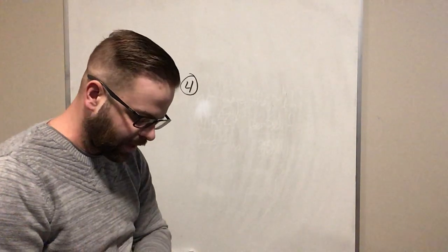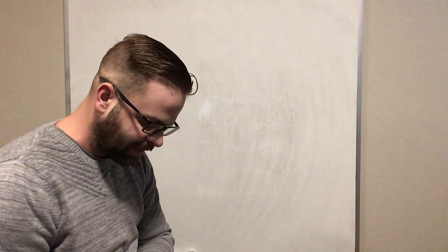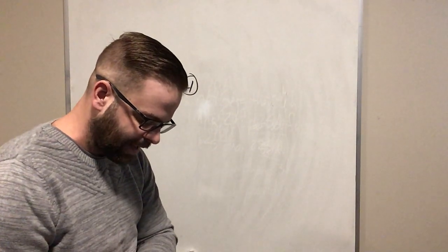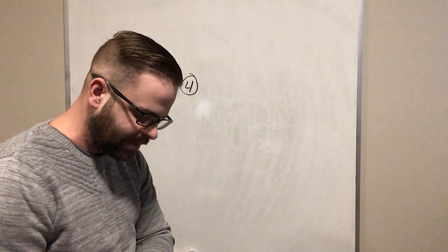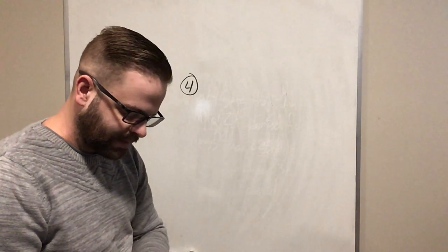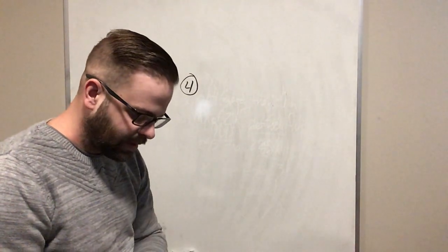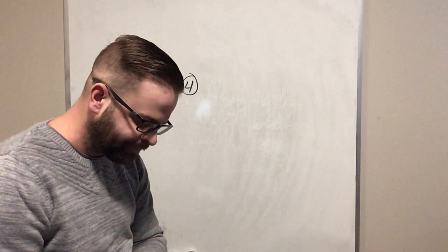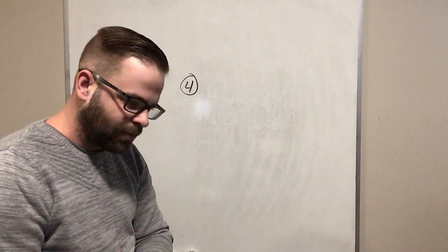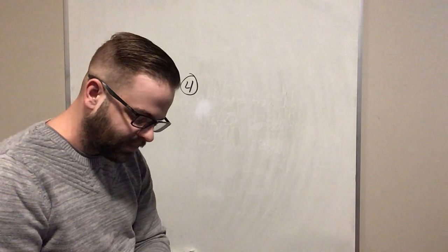Number 4 says a load of a cyclic or intermittent nature shall be classified as continuous unless it meets the requirements of sub-rule 3. So basically, a cyclic load turns on and off in a set period of time, or an intermittent one comes on spontaneously. That would be heating loads, like electric heat, a baseboard heater, or a boiler, something along those lines.